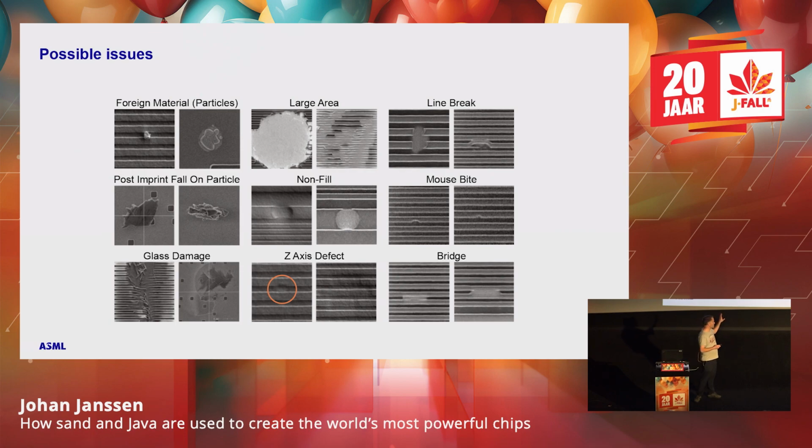And so you have a lot of these kind of defects, and there are basically two other categories how you could look at it. You can have issues on one wafer, so let's say a dust particle on the wafer, then maybe some chips are broken. But if there is an issue with the reticle or with the laser, then every wafer that goes through has an issue. And that's of course a way bigger issue than just one wafer, a few chips that break.